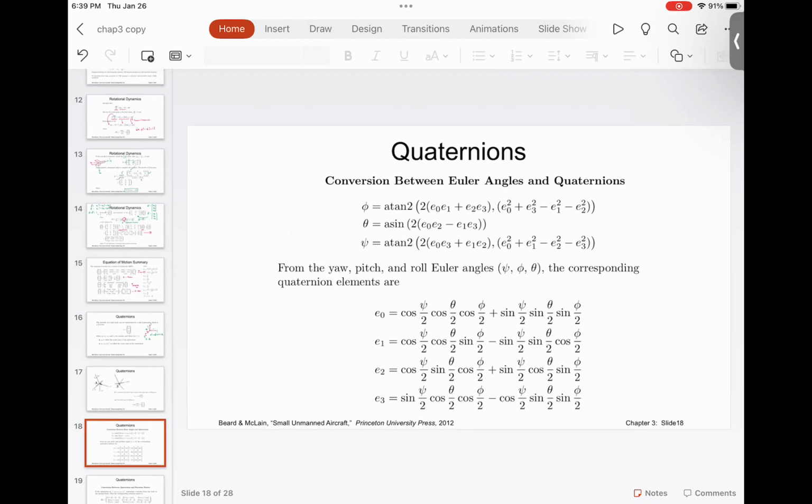So what I want to do is show you, and again, you don't have to remember all these equations. MATLAB has built-in functions, or remember the tools folder that we copied onto our Simulink folder that has this code written. The only thing I want you to understand is, if you are solving in terms of Euler angles, it is possible to construct the quaternion from Euler angles. So input is roll, pitch, and yaw, and it will give you a quaternion, E0, E1, E2, E3.